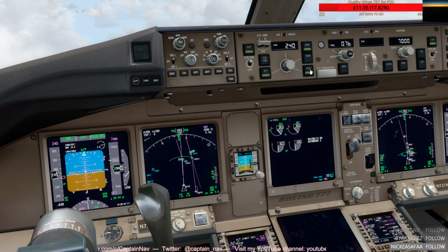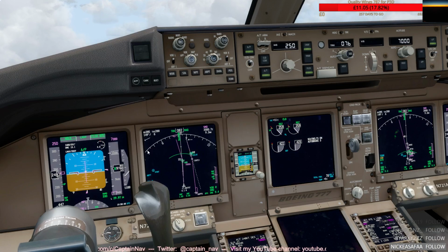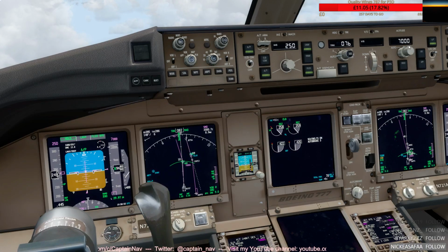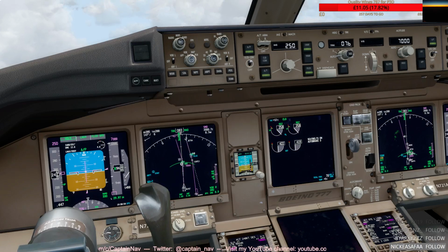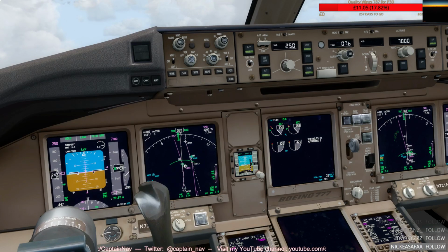So yeah, now I'll go flight level change, maybe keep 250 knots. That was the FMC reducing at 240. Cabin crew, prepare for landing. And now because I've got 7,000 feet here anyway, I know that I'm not going to go lower than 7,000 feet, even if the descent I'm creating is maybe going to be faster. Because I've got 7,000 feet here in the altitude window, it's going to protect me against the 7,000 at Santa Monica.